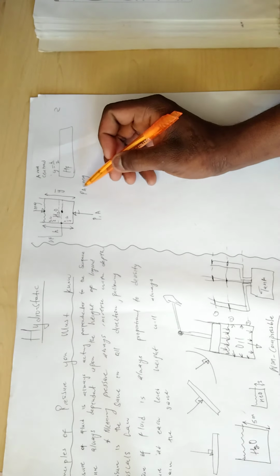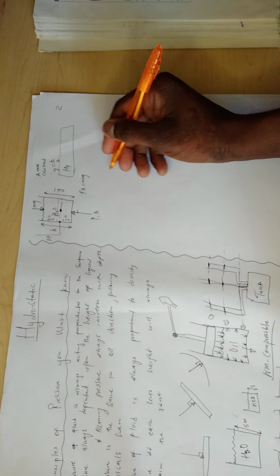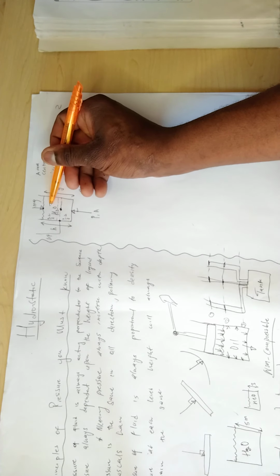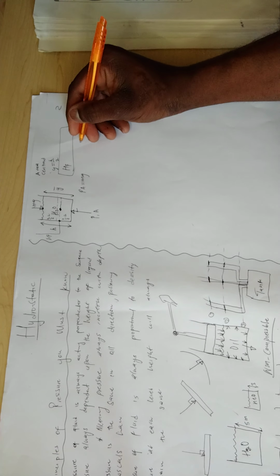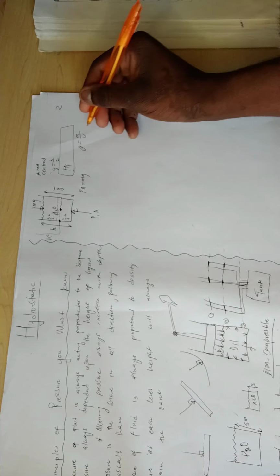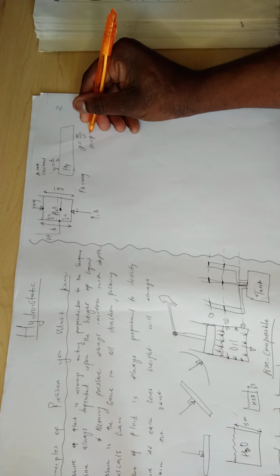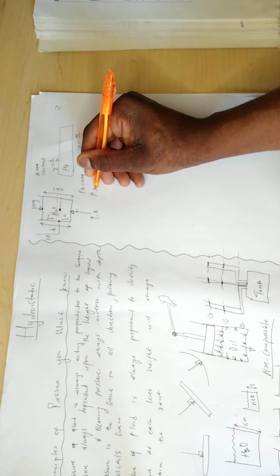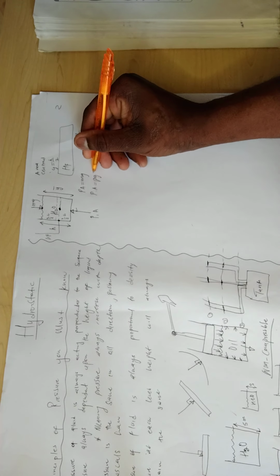But we need to break this out so that we can find values that are here. Let us break mass out. Where does mass come from? Mass comes from the weight of the water, meaning if we can find the density and the volume, we can get the mass. Density equals mass divided by volume. We know this formula. Then let's make mass the subject of the formula: mass equals density multiplied by volume. So we can come here and say pressure multiplied by area equals density, gravity, and volume.